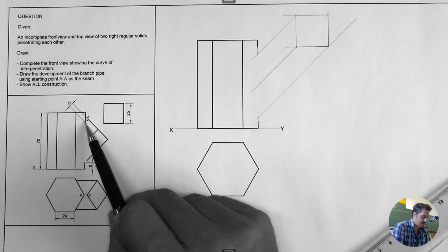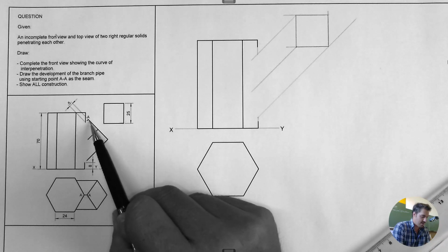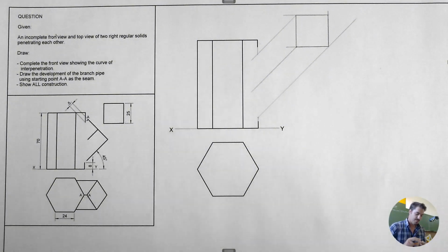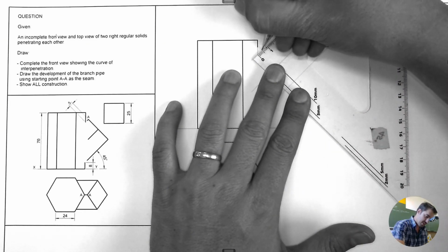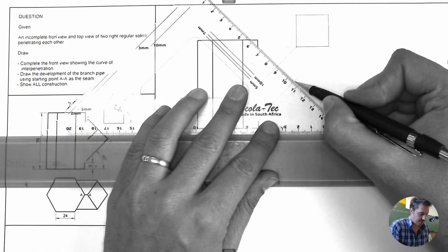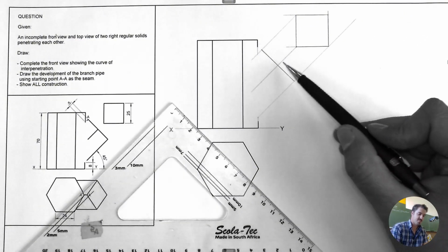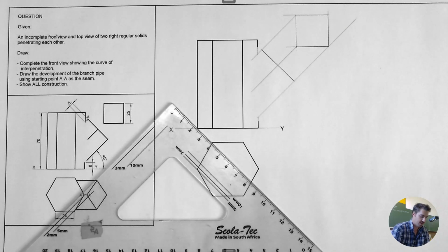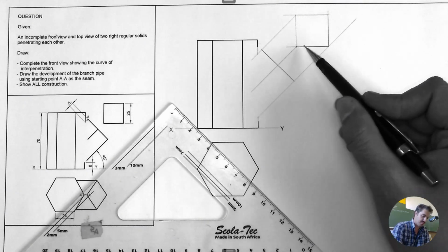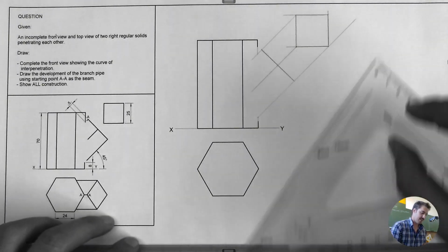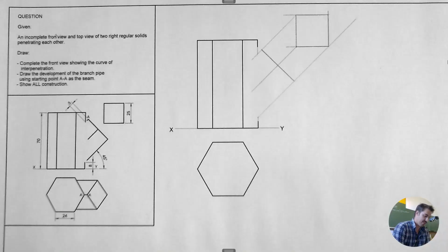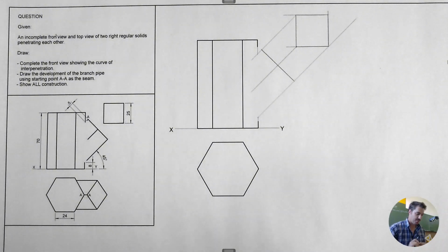And now I can go ahead and measure 5 millimeters there, and then this will also be a 45-degree angle because it has to be perpendicular to the original angle that I used. So from here to there it's 5 millimeters and then a 45-degree angle. So here you can see the space that I basically have left. So this could have moved a bit closer or a bit further away. It would have been the same story. Alright, so once I have this, I'm just going to leave this hanging just for a minute because I would like to complete the top view first.